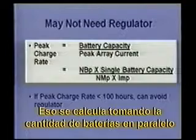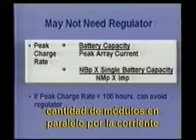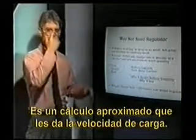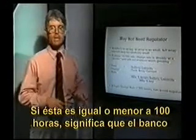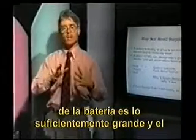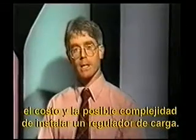You calculate that by taking the number of batteries in parallel times the capacity of any one battery and dividing that by the number of modules in parallel times the max power current of a module. It's a rough calculation. And you'll get your charge rate. If that charge rate is equal to or less than the 100-hour rate, then you're in a situation where your battery bank is big enough, your array is small enough, and you can think about avoiding the cost and the possible complexity of installing a charge regulator.